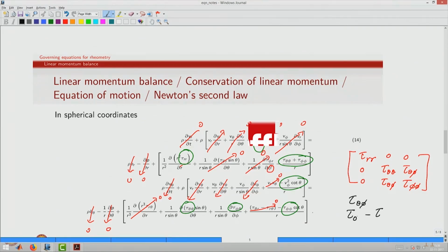So, we will have to manipulate the overall fluid mechanical governing equation, and then try to see what will be the variation. Now, since I said there is no pressure gradient, what we need to remember in the case of viscoelastic fluid flow is that pressure gradients can arise even though they have not been applied.